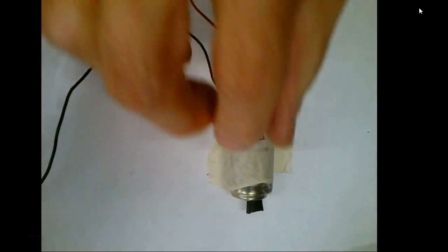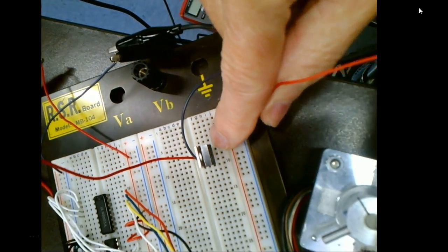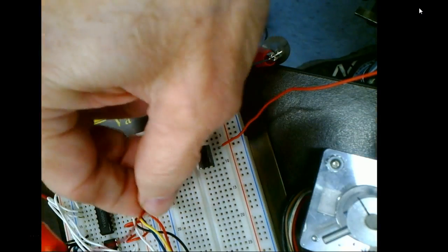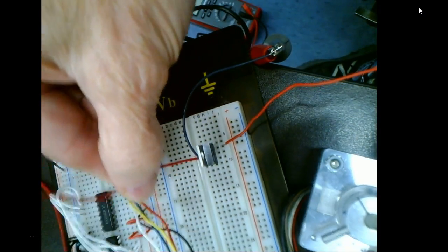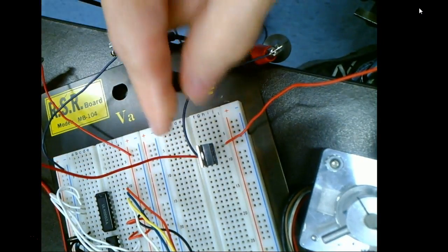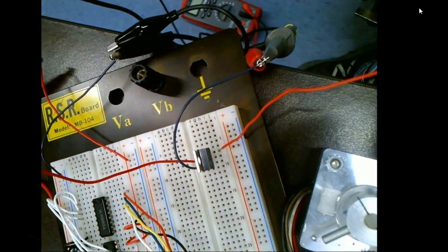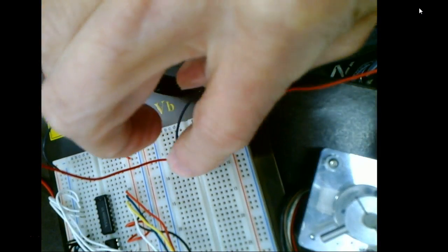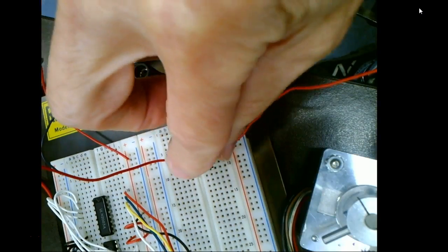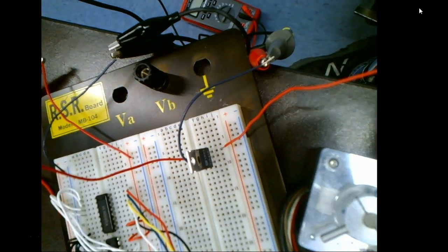So I've got a DC motor right here, a little tiny one, and I have it hooked up to my transistor right here. So this is the motor. This is the power lead coming in to the transistor. Transistors don't create current, they control current. And this is the lead right here that's coming from my function generator that's turning the transistor off or on. This guy here is rated at about 6 amps, so I could run a pretty good sized motor on that, but that was just the one that I grabbed.